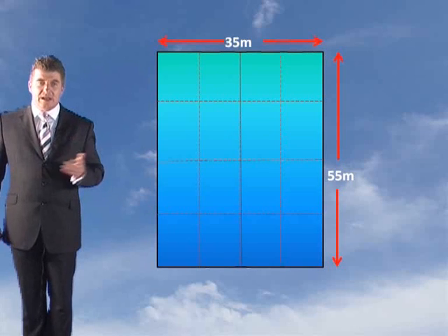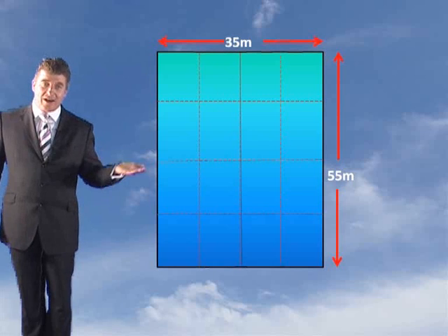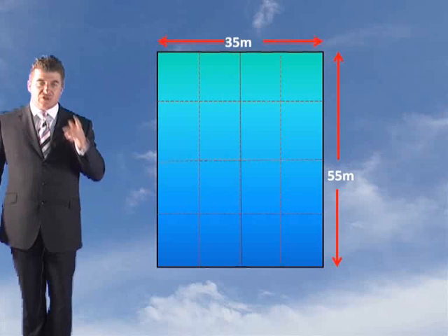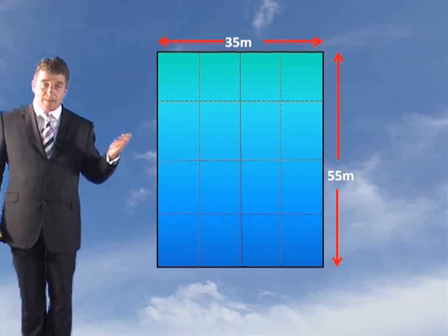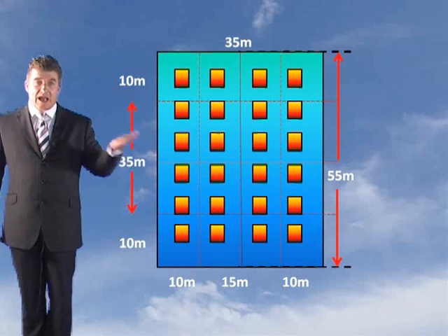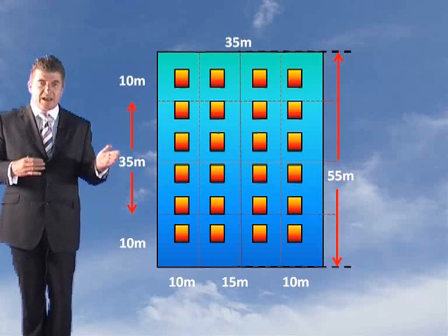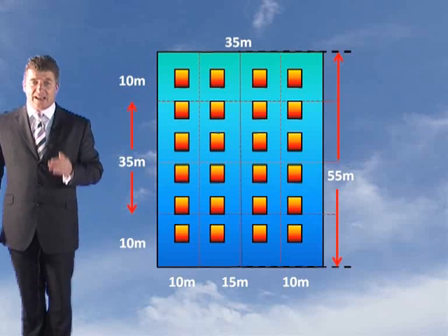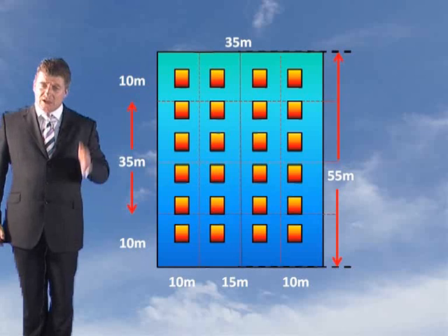That's what we'd need. Now in this case, we know we need 24 anyway. So do you understand? In a way, we need more than what the stagnation rule says. So now we've got to have 24 ventilators somewhere on here. And this is how you do it. You just spread them out, axisymmetric, all the way around the building, spread it out in the reservoir. So this is what you'd need, 24, and it satisfies the stagnation check as well. So that covers step 8.